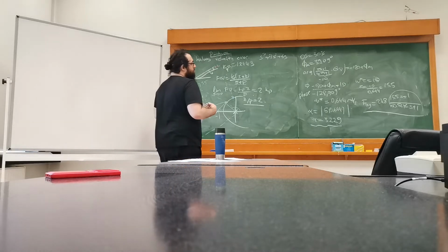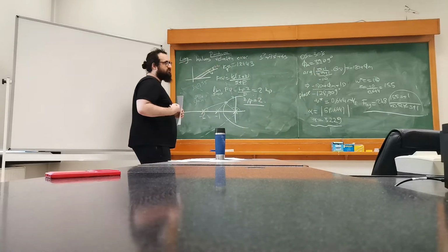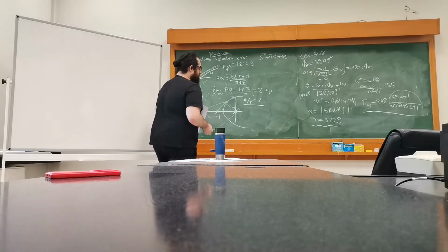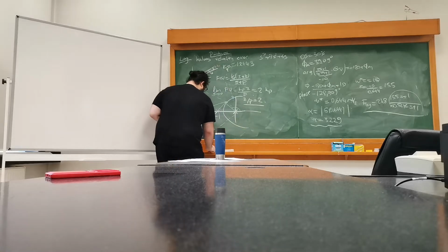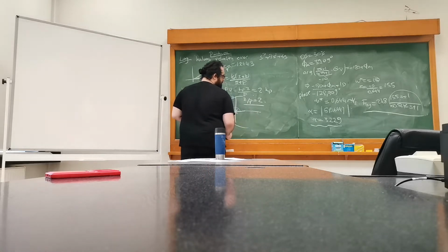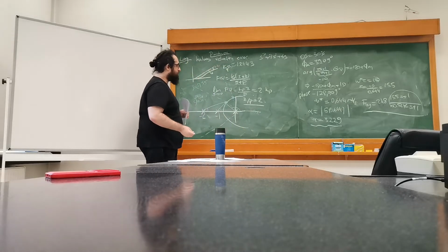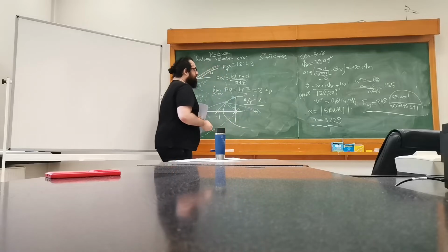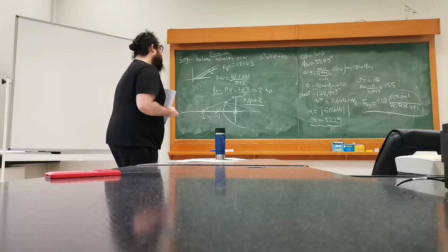And therefore, something that relates to this here is 10 degrees. The difference shouldn't be greater than 10 degrees. So if I'm adding a pole and a 0, it shouldn't really change that much. Now, let's, for an example, introduce it somewhere here. So since it's a lag controller, we'll have a 0 and a pole. Now, if you look at this, you will see that the difference here will not be that much. But the problem here is, of course, it's on the right half plane, so it's not really what we want to have.